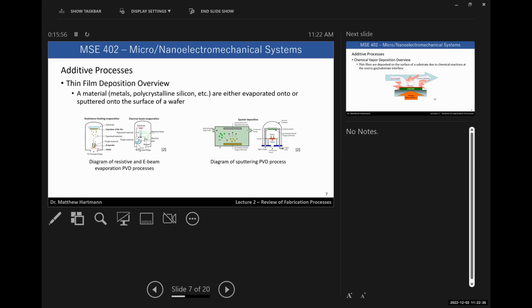Sputtering is effectively you're shooting ions at your target, knocking off chunks of material, and then you're trying to draw those knocked off chunks of material to your substrate to form a moderately uniform layer. So it's called sputtering because the bits of material sputter in fits and starts and clump up on the top of your surface. It works a little faster than evaporation.